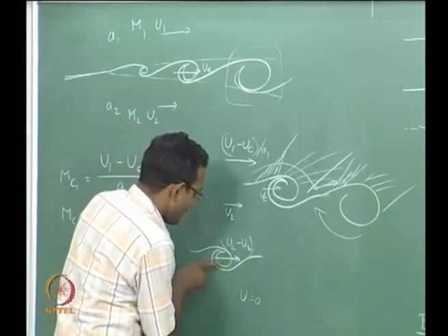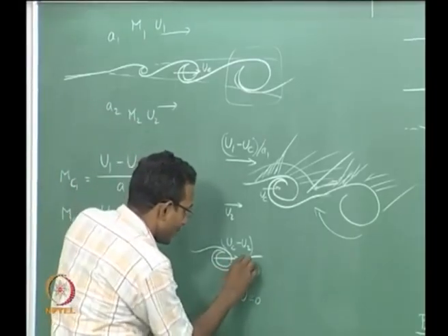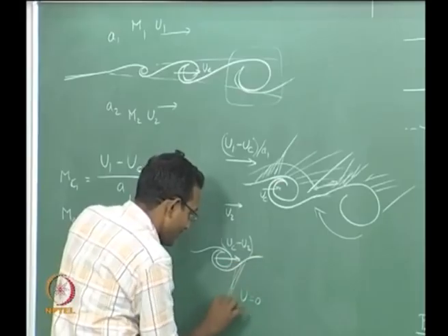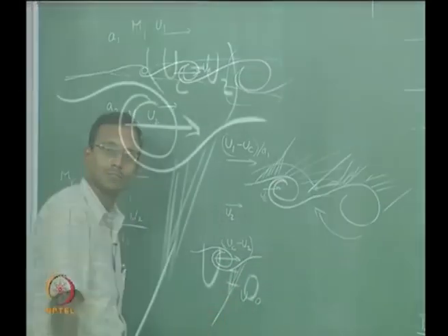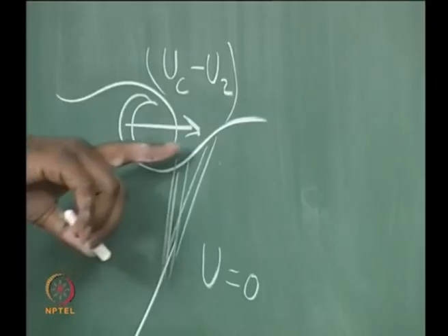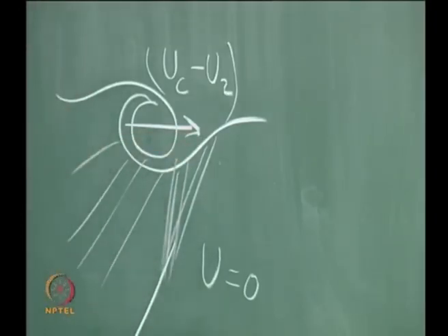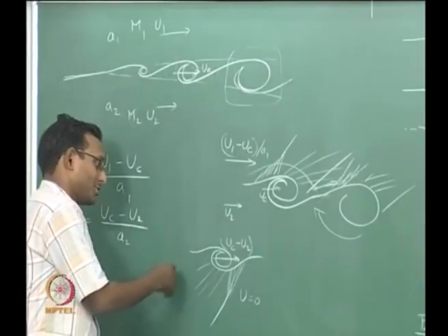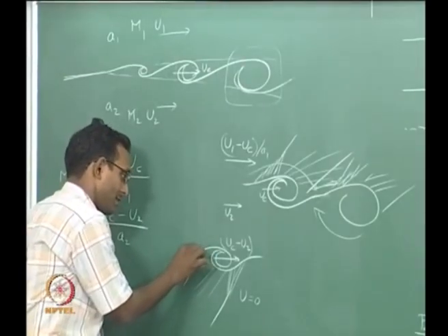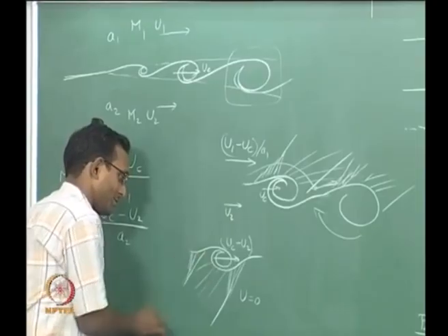Now what will happen, this is a body going like this, it is going to start forming shocks here, a set of compression waves forming shocks, and then after that the body turns around, there will be expansion, and then the next shock, and then a set of compression waves again forming a much stronger shock.